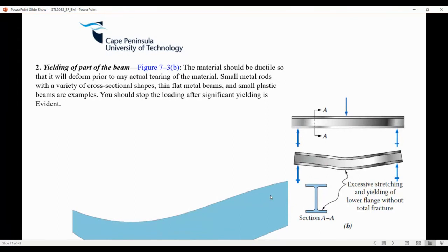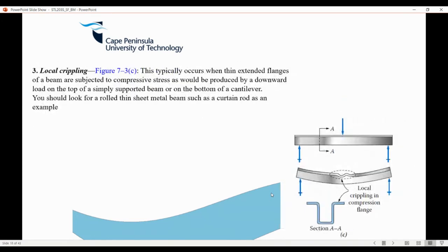It's bending. Fantastic. What you're seeing in this particular section here is the beam passes yield strength basically. So let's assume a yield strength of 355. You're seeing this beam with induced stress of around say 400 megapascals. So that's why it's not completely broken. However, if you keep on loading the beam and let's say the UTS is around 500, it's going to break. That's the idea. So you can see a typical shear failure, typical bending failure.